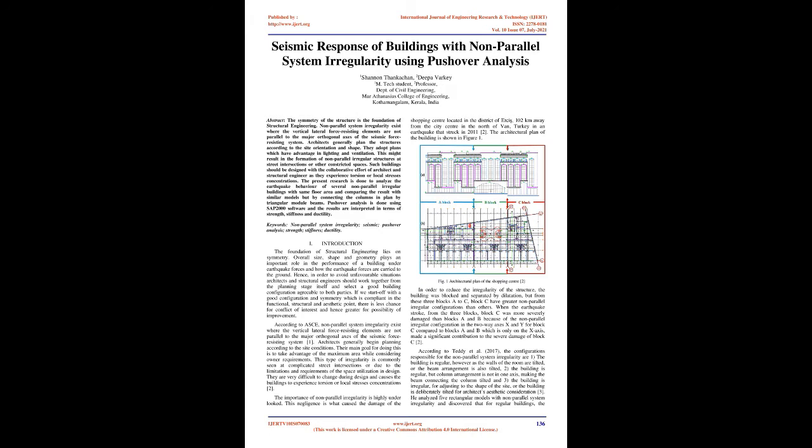stress concentrations. The present research is done to analyze the earthquake behavior of several non-parallel irregular buildings with the same floor area and compare the results with similar models, but with the columns connected in plan by triangular module beams. Pushover analysis is done using SAP 2000 software and the results are interpreted in terms of strength, stiffness, and ductility. Keywords: non-parallel system irregularity, seismic, pushover analysis, strength, stiffness, ductility.